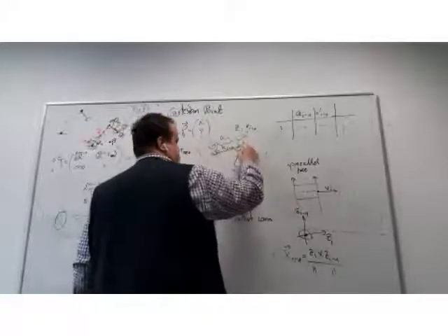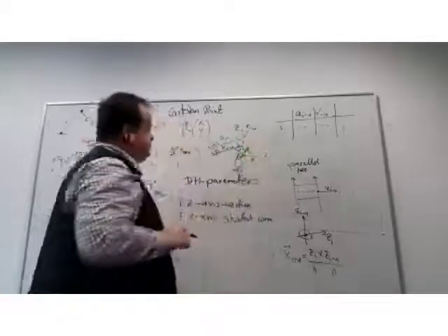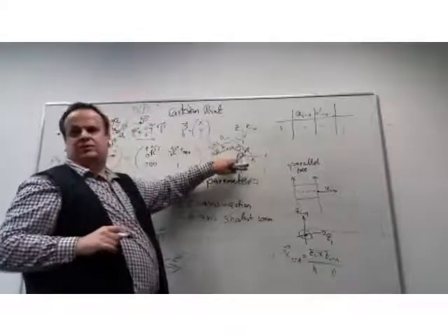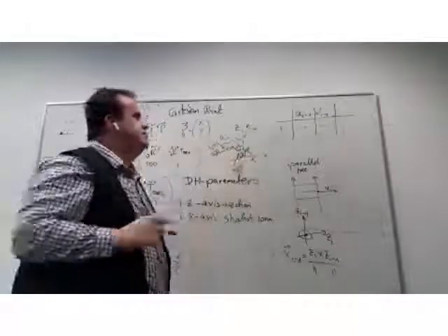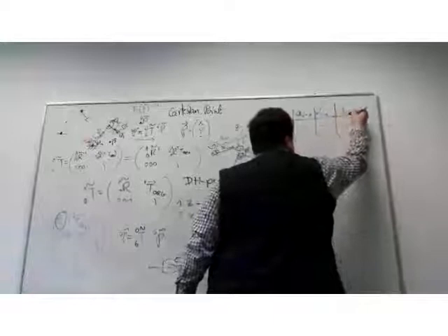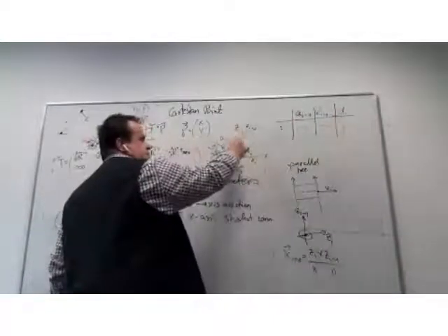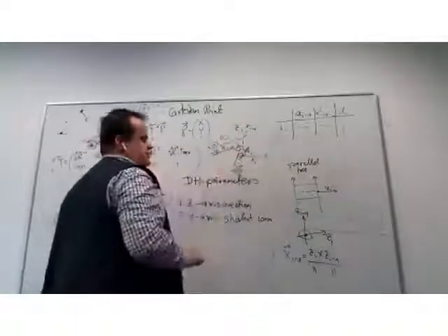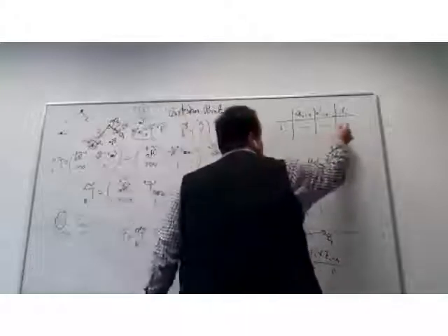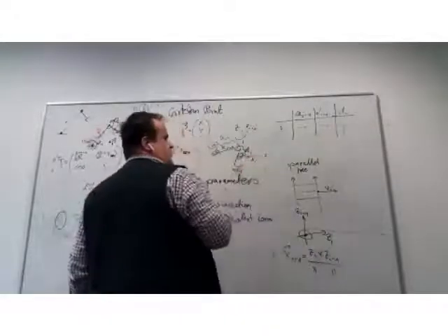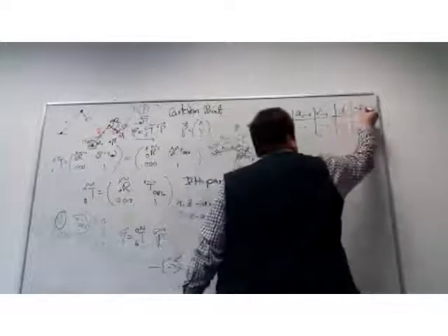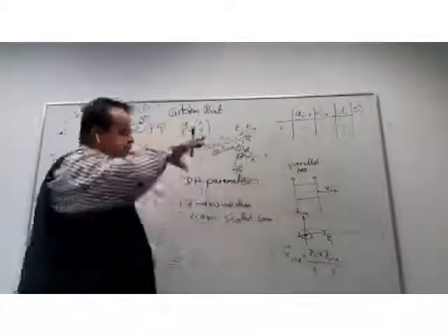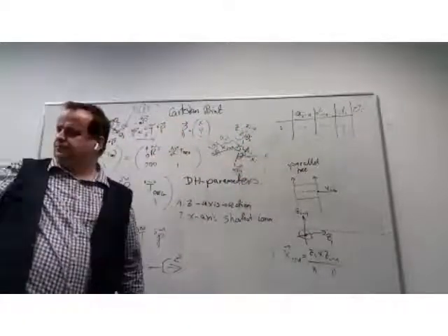And now I need to go the distance between where the previous x intersects the z-axis and where the new origin of the next frame starts, down or up. This really defines if I go in the positive d direction or the negative d direction; this will be some negative amount of d I need to travel here. And to end up in the new coordinate frame, I need to rotate by the angle theta i, which defines my current orientation of the joint.